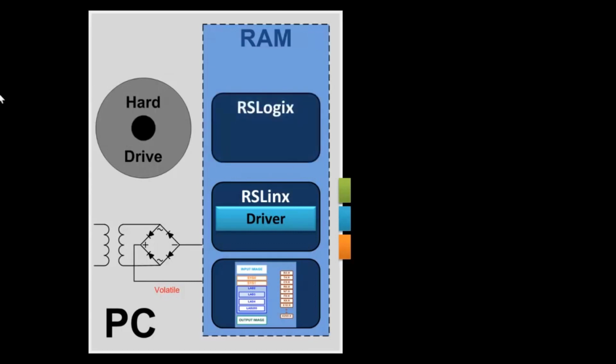So you open up RSLogix Micro Starter Lite, you bring in a project, and at this point, this looks exactly like what you would have out in the field if you had a laptop with RSLogix open and RSLinx open, a driver configured, and there was an actual PLC in a machine. You have yet to connect to that PLC. Even if you hook up a cable, until you actually go online or download or do something, you're not connected to that PLC.